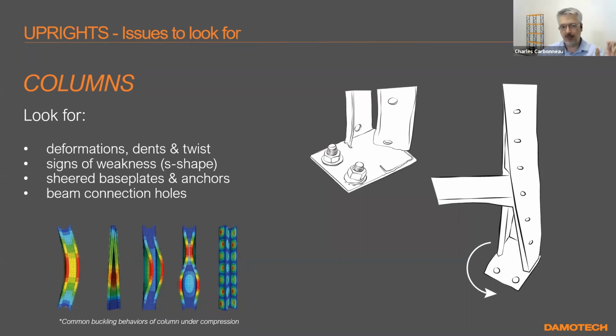Maybe we are not that tolerant. Maybe a 1/4 inch would be the maximum twist that we would allow. So twist is something that has not been super well studied on the behavior of columns, and the buckling of these columns in compression and torsion capacity is somewhat limiting the capacity very much. Sorry, I'm getting into the engineering details here.